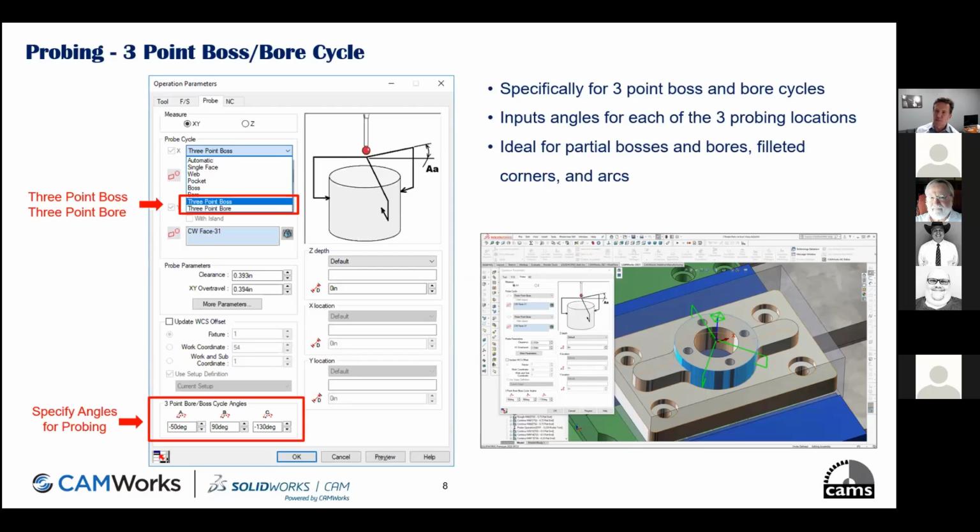So in other words, a company might have a stub length drill, a jobber length drill and an extended flute length drill in their database. And then how would they handle each of those scenarios, Brian? Yeah, if they're using a stub length drill, obviously the flute length is different. They could set the peck amount by that flute length so that it's not taking too big of a peck to bury that flute length in, which is awesome.